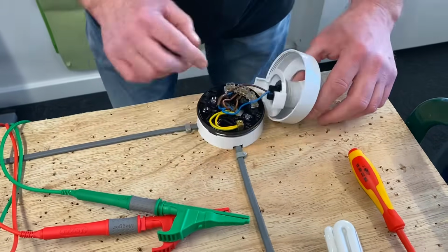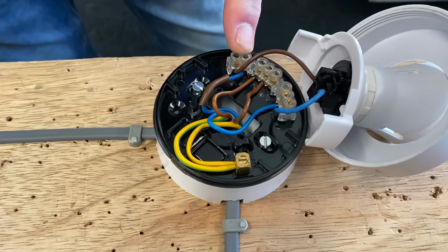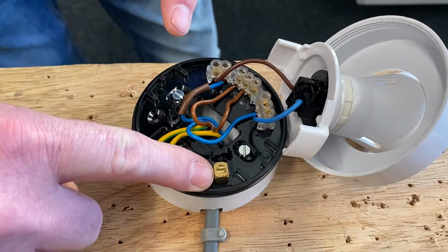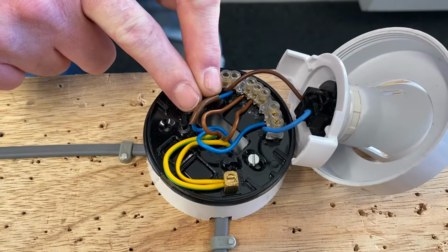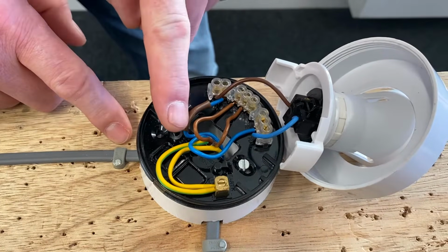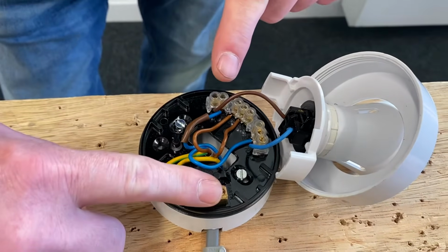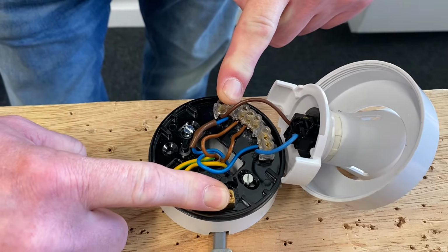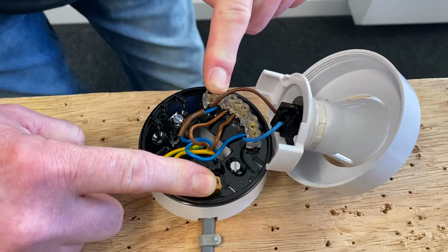So if we undo here, and we open it up, we can see we've got our connections here. Hopefully we're familiar with the 3-plate method from many videos that I've done and time training in college. So we've got our circuit protective conductor here, and we're going to be going on to our switching line conductor so we can prove that the switch will operate in the line conductor. It's not a neutral, it's got brown sleeving on, it is a switching line, and we've covered that many times on the channel. So I'm going to measure between here and here. I'm going to look at the reading, I'm going to operate the switch to hopefully see full scale deflection, and when I see that full scale deflection I know that switch is operating.